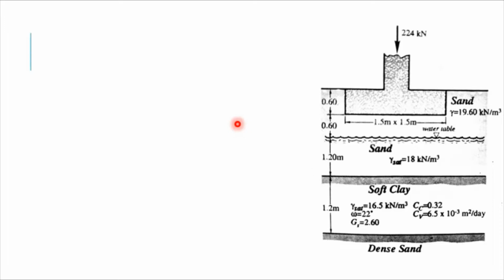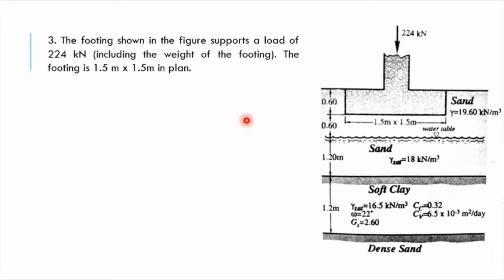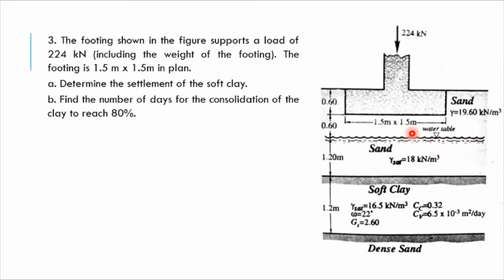Next problem. So this is an example of settlement due to additional load by footing. The footing shown in the figure supports a load of 224 kilonewton, including the weight of the footing, and the footing is 1.5 meter by 1.5 meter in plan. So we have to determine the settlement of the soft clay, the number of days for the consolidation of clay to reach 80%, and the settlement after 20 days.